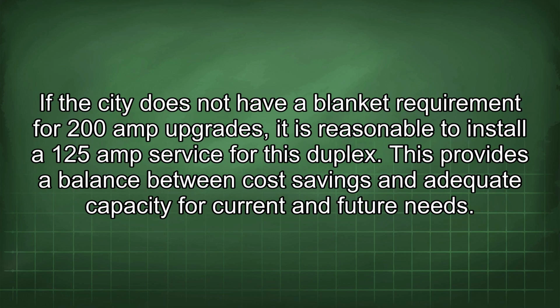If the city does not have a blanket requirement for 200 amp upgrades, it is reasonable to install a 125 amp service for this duplex. This provides a balance between cost savings and adequate capacity for current and future needs.